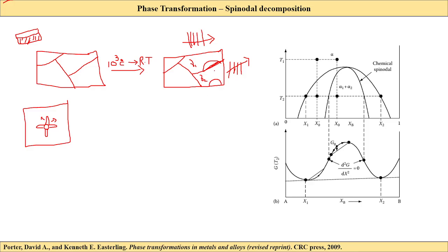Now in heterogeneous nucleation there is already a surface, there's already a grain boundary. The grain boundary doesn't follow any symmetry, because the symmetry changes from one point to another, from grain gamma 1 to gamma 2. So there is no specified symmetry at the grain boundary, which is nothing but a totally random arrangement of atoms.